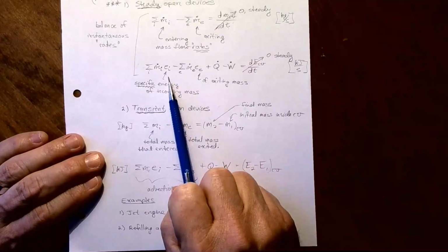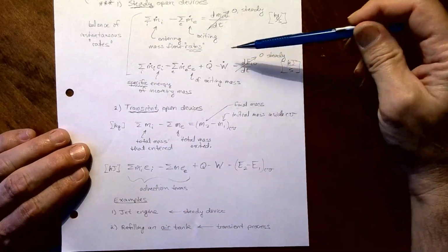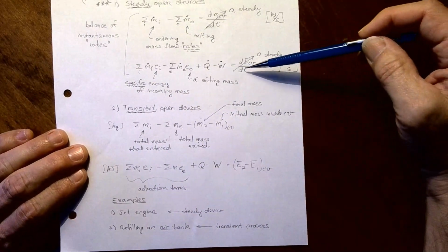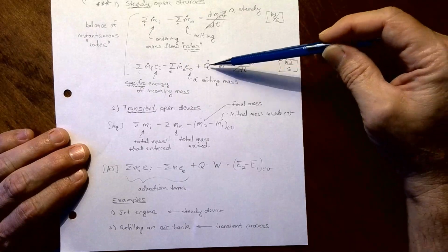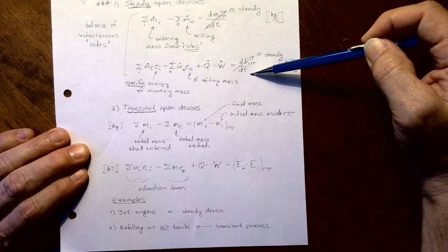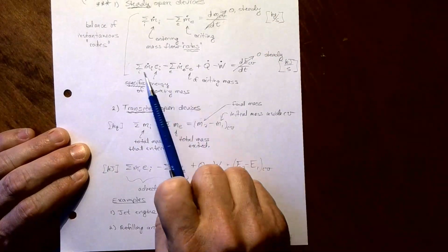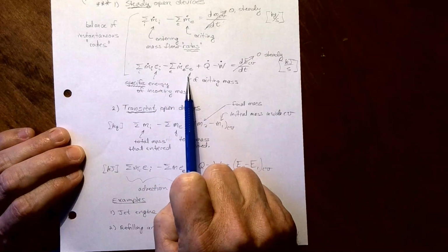For conservation of energy, or the first law of thermo, the equation will look like this. If you notice, Q minus W equals delta E was a closed system energy balance. Now on a rate basis, it's just Q dot minus W dot equals dE dt. If we have mass crossing the boundary, then that mass that's entering brings energy with it.